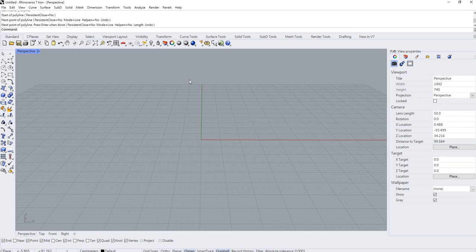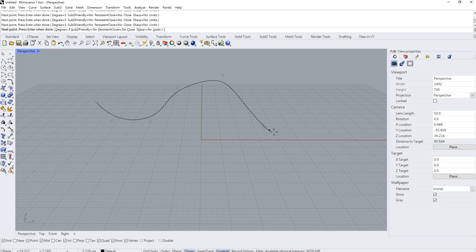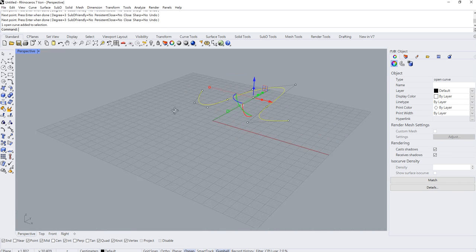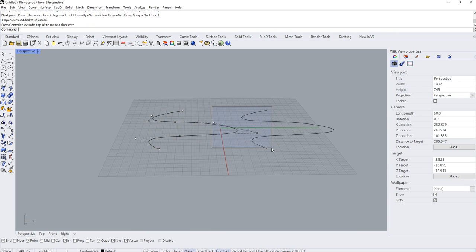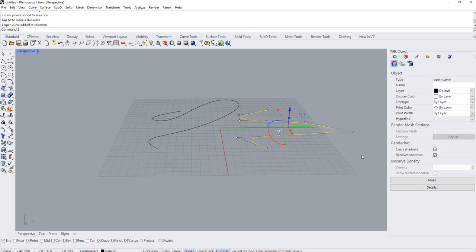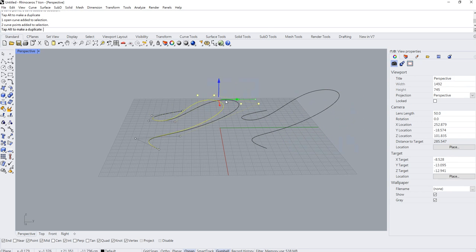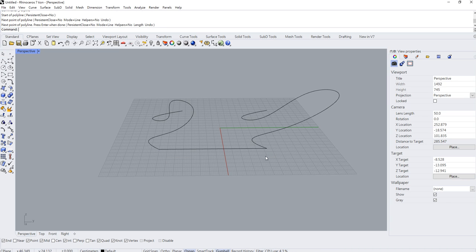Inside Rhino, when we are working on our model, basically everything is composed of multiple commands. For example, if you remember, when we were working on sweep 1, let's do the sweep 1 in a very quick way. Select all the curves, and just draw a linear line and use sweep 1 or sweep 2.